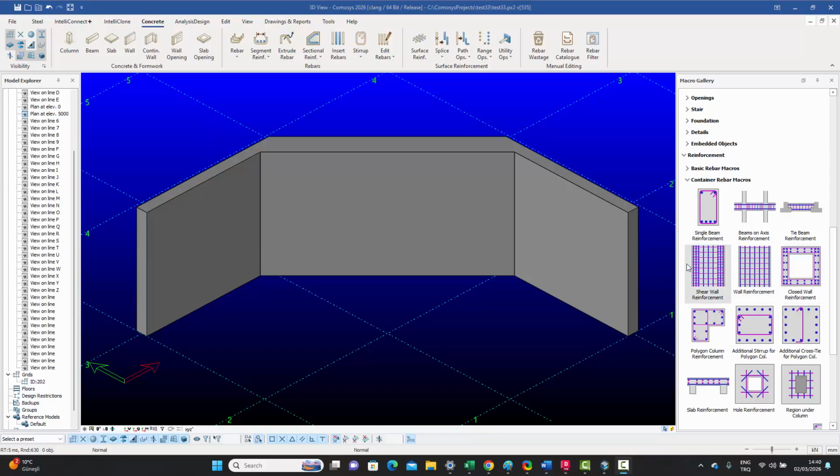And if it's a shear wall, because shear walls have special requirements, they've got these zones at the end where you have special rebars, they're like hidden columns inside the shear wall. So that's also separate. But at the moment, we'll be focusing on this one in the middle.